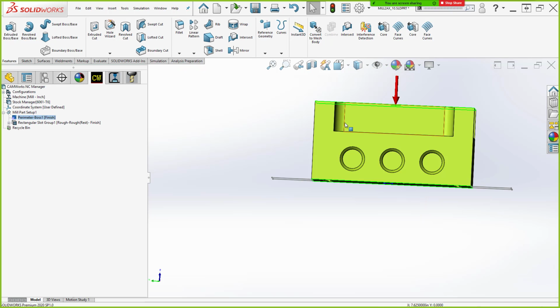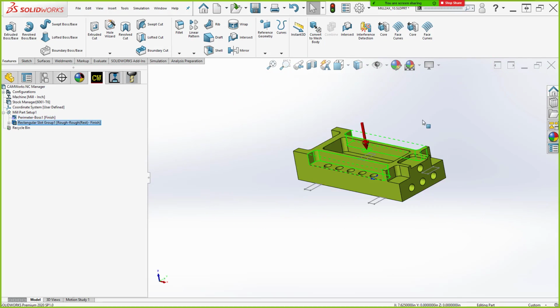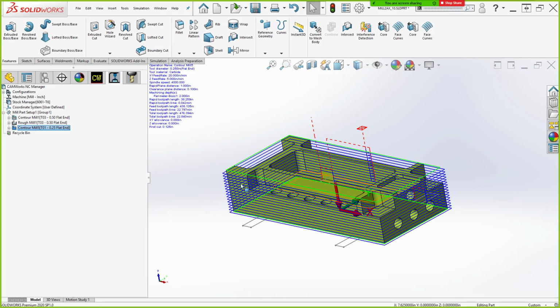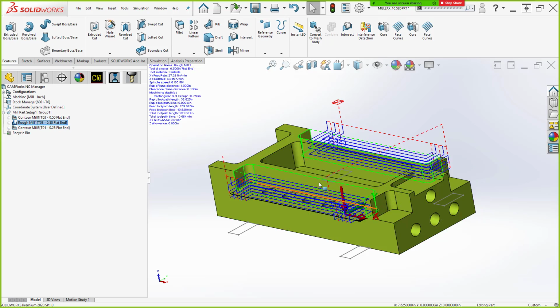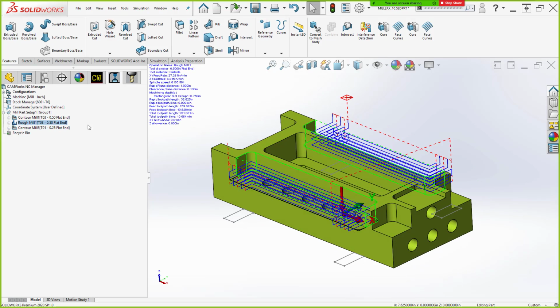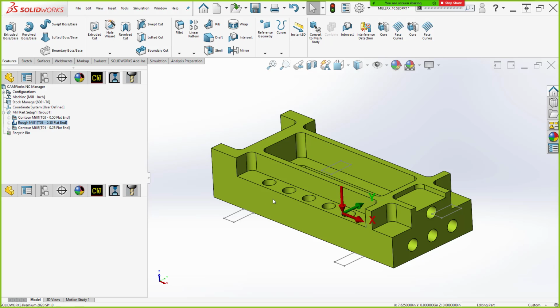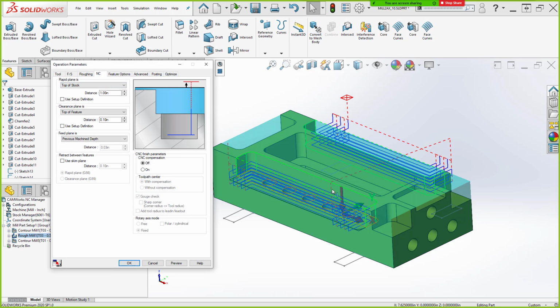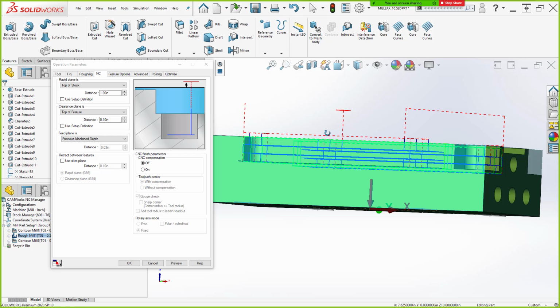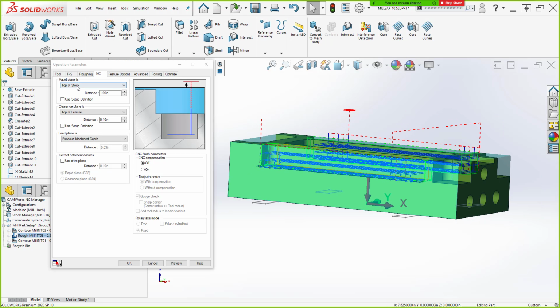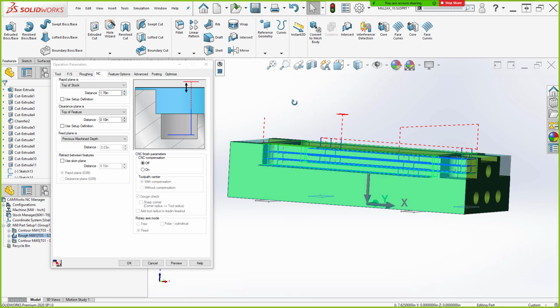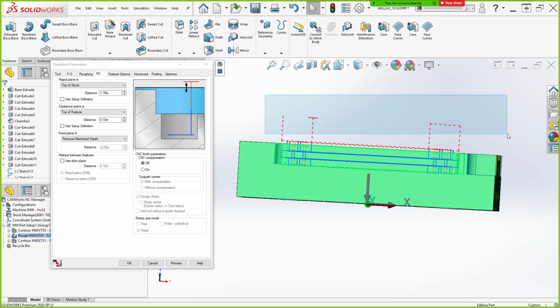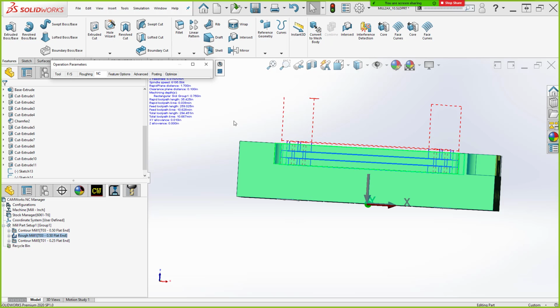It had these slots earlier, right, that we were programming. Now we go look at the rough mill that's cutting that guy. Let's edit him. Rapid plane. A lot of these are defined with respect to existing geometry, so top of stock plus 1 inch. Right, as I increase that value, what we'll see are these kind of 4 peaks up here. The entry and the exit, and then this transition line between the features. That's what we're affecting with rapid.